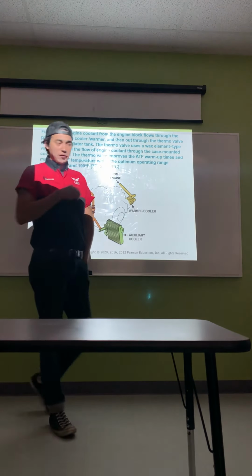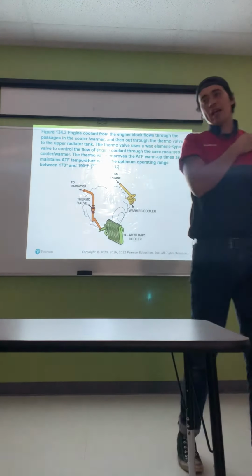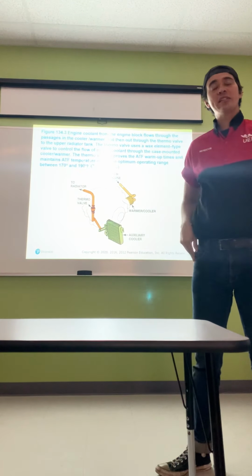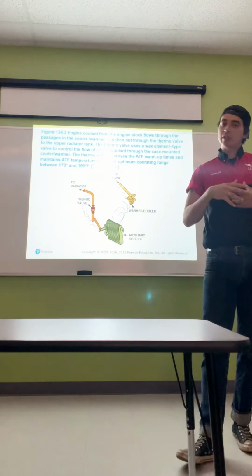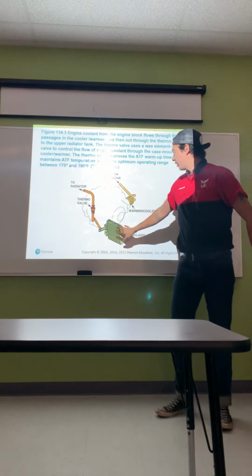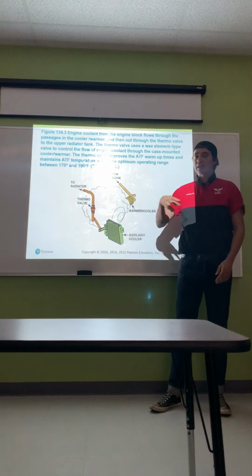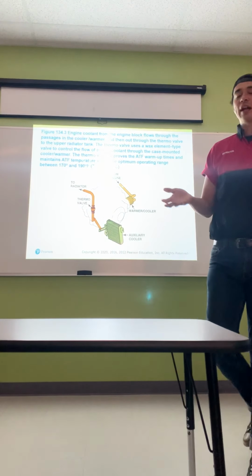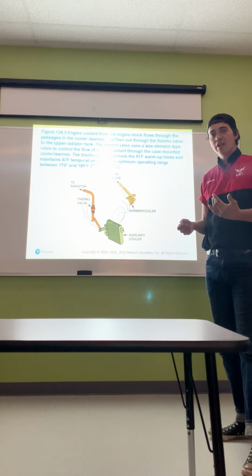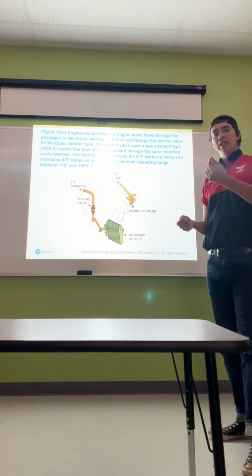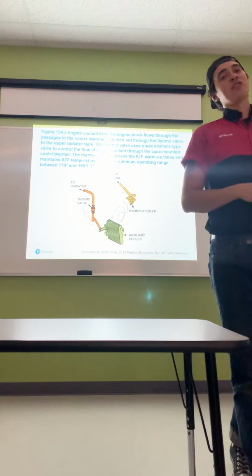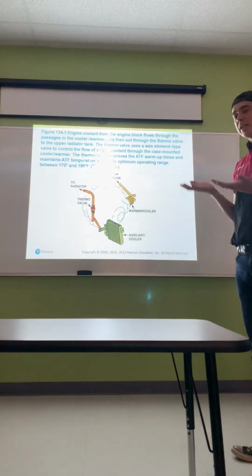So the thermal valve is kind of like a thermostat for an engine. As coolant goes through, it keeps the coolant inside the engine block while it's waiting to warm up. Once it warms up to a certain temperature, then it will allow it to go through. The same thing comes into play with an auxiliary cooler. The thermal valve will open and close as it sees fit as far as temperature. So if it's too cold, it's going to allow the fluid to stay in the transmission longer to warm up, and as soon as it starts to warm up, it's going to open the valve and allow it to come through the cooler and go back into the transmission. So it's to help monitor and maintain temperature.